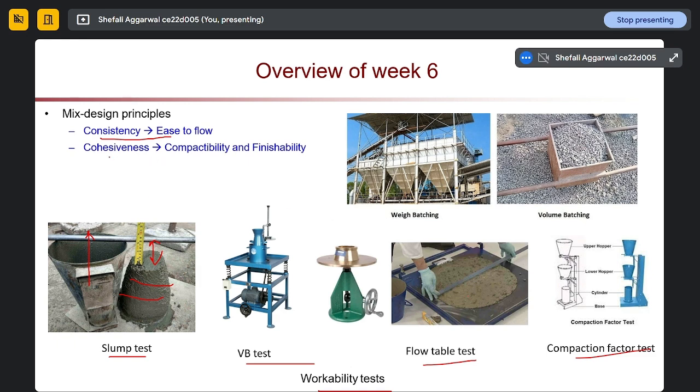So next, now that we understand what exactly concrete is, what are the different types of concrete we are dealing with? First is plain concrete. We see it on roads and in structural elements which do not take up loads, where we are using plain concrete. Mainly roads, or just a park area, stairs area, where there is no provision of taking up the loads from the superstructure.